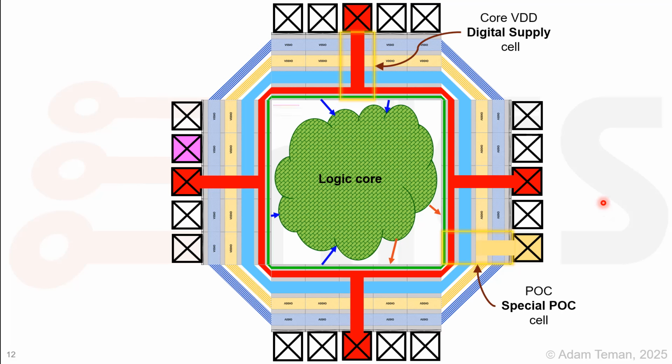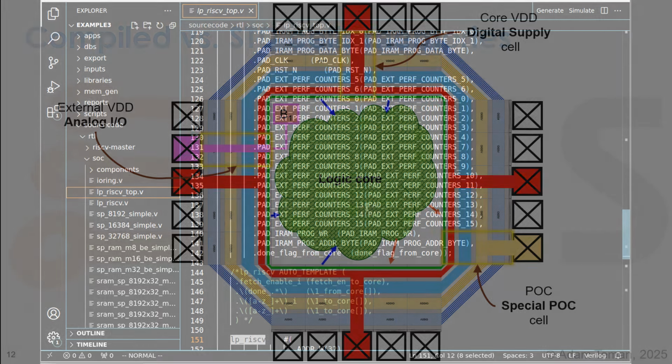The next thing is, what if we have some sort of power domain over here, an analog block that needs a special voltage? What we're going to do is put an analog voltage connected over here and use an analog IO that, as I said, is just a wire. This is not a buffer, it's not a digital block, it's just a wire that connects whatever voltage we bring in from outside to our analog block over here, which gets some voltage that is neither VDD nor ground. This guy is going to be ESD protected, but it is not going to be directly connected to VDD or ground. It's not going to drive a 0 or a 1. It's going to be ESD protected, but that's it.